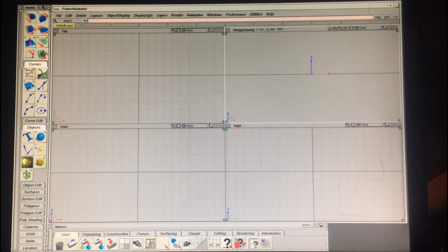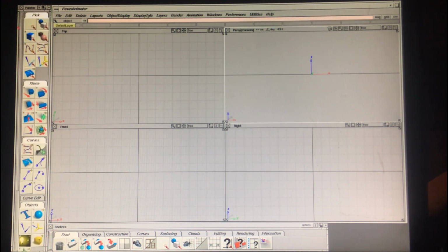First thing that I always want to cover in all of my tutorials is that it's two tiers. There's basically three big things that you do, but the first 2 are how to navigate the 3D views, how to get around those, like panning and zooming and rotating through them, and then it's about object creation. And once you have objects, then you need to manipulate them. So that's like the move, rotate, and scale tools.